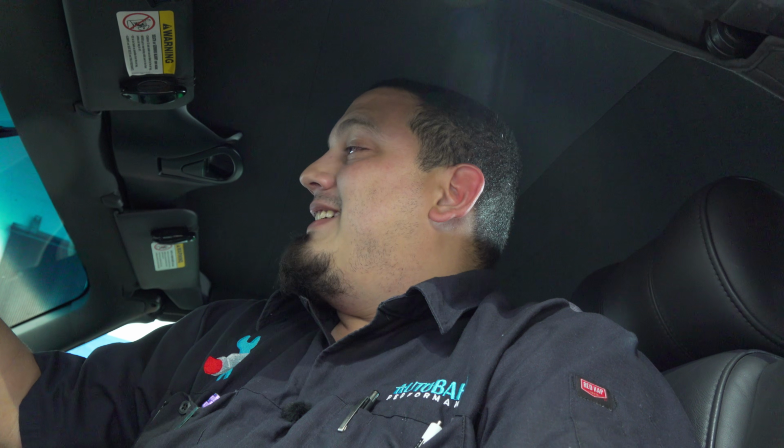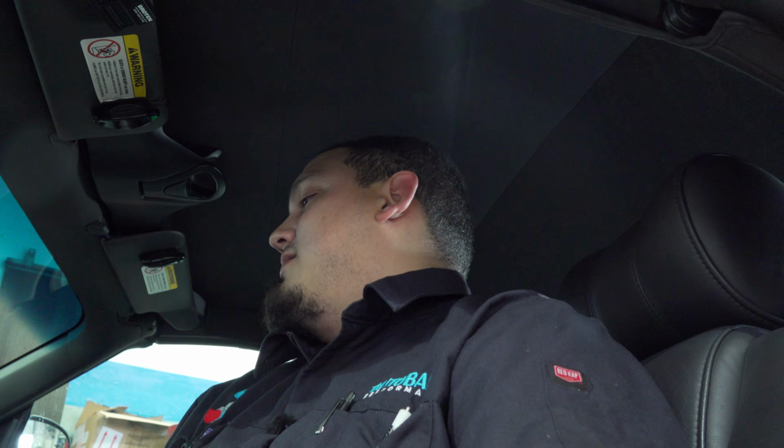A lot of people are actually replacing clusters for this, and that would be a big mistake because used, these clusters are like $800-900 even for this year. This is a 2002, and it goes about $800-900 used. And the patch system, I believe, is involved with the cluster, so it will not start. So they have to program the whole thing too, just to find out that that's not going to fix their problem. So never guess, always test.